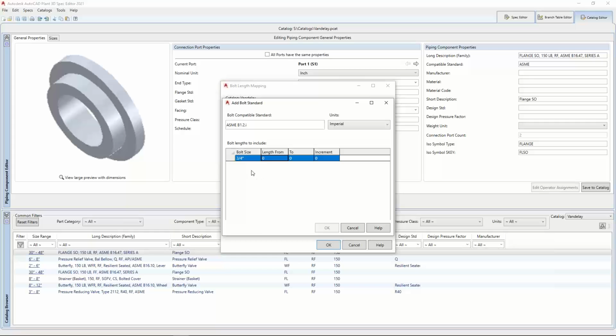And here's rule number 2. Always use the inch sign. That also has to match the bolts. And since the bolts are labeled as 3/4 inch, you have to use the inch sign. If you just put 3/4, it won't work. Here, though, you don't use inch signs. That's just the way it works.